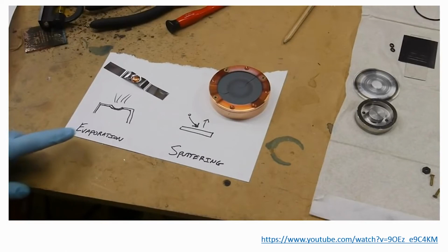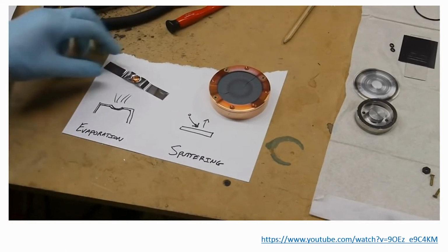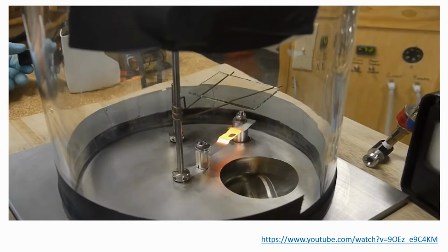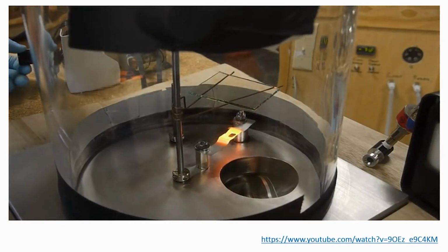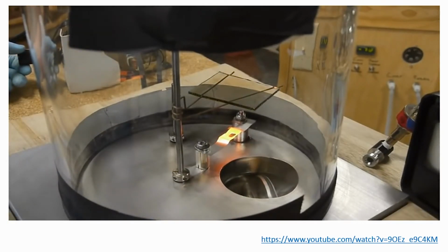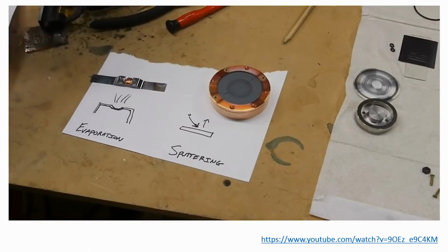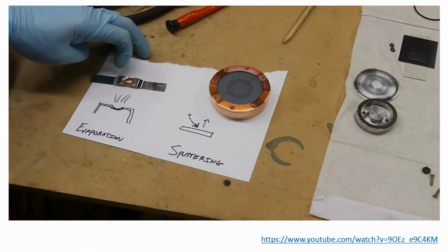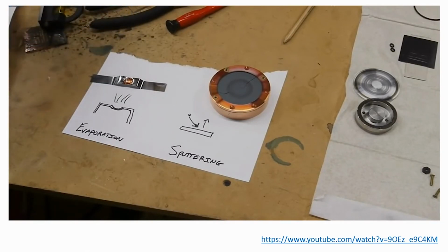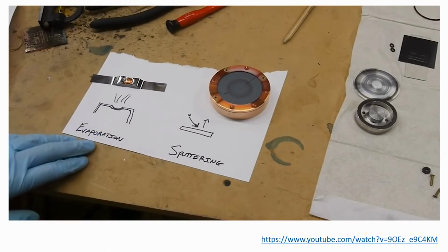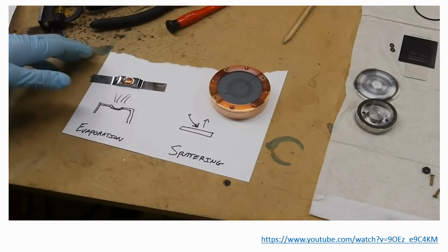In a previous video I described the evaporation process, and this entails heating up the material with which you want to make the coating, and typically that's done in a metal boat like this. What we do is pass a really high current through here. This thing becomes very, very hot, white hot even, yellow hot, and the material here evaporates and then condenses on the thing that you want to coat. This is roughly analogous to boiling water in the kitchen and then noticing water droplets condense on a cold window. The downside with this is that you have to heat up the material to that yellow hot temperature.